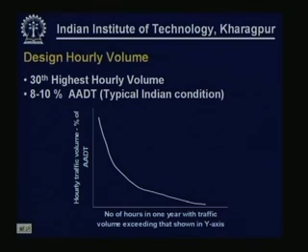So, that is also again a difficult component. So, what is done? Normally the 30th highest hourly volume is suggested as design hourly volume in India.